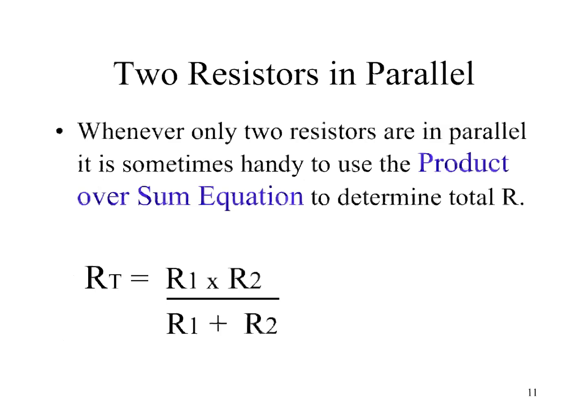Now there is product over sum equations for resistors all the way up to infinity in parallel, but the thing is it really loses its advantage for anything, I would say, beyond 3 or 4 parallel loads. If we look at the equations for even a 3 parallel resistance, the equation becomes far more involved.